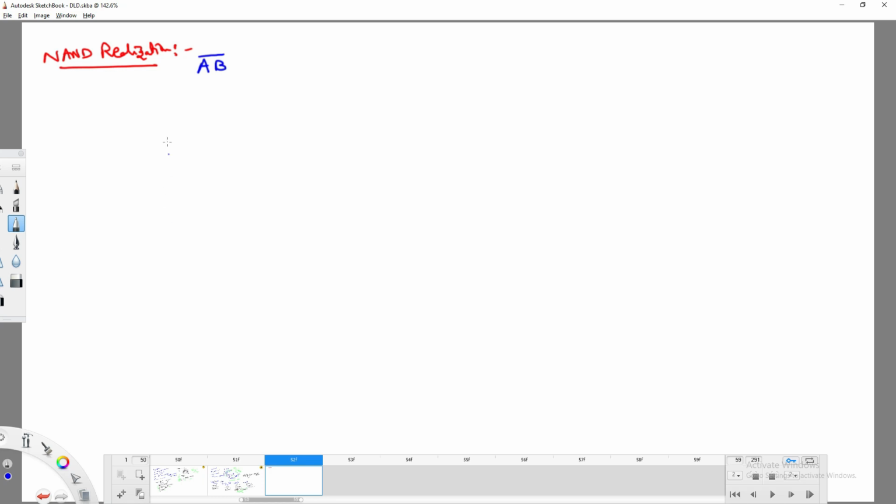Guys, we have various kinds of gates. One is the NOT inverter. What is the property of a NOT inverter? If you give A as input, you need to produce the output A complement. For that, the basic symbol we have gone through is like this: input A, output A complement. Okay, good. Now, can we implement this NOT gate with the NAND gate?